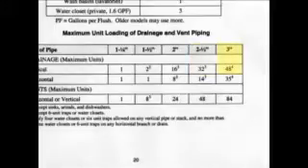This means we still have to go yet another column to our right. At 48, we have a footnote 4. Only 4 water closets or 6-unit traps allowed on any vertical pipe or stack, and no more than 3 water closets or 6-unit traps on any horizontal branch or drain. So that footnote does not apply since we only have 2 water closets. So we would be restricted to at least a 3-inch pipe. The answer would be 3 inches for number 2 over on page 21.